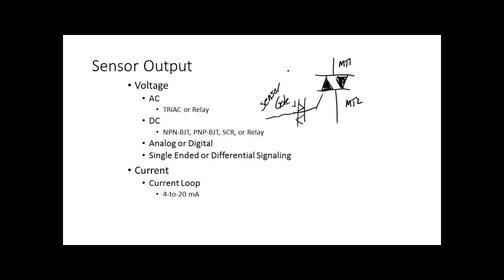So that means as far as how fast we can switch, solid state devices are far faster than relays. Now, as far as turning lights on and off, we have no problem. But some of the things that we run into in controls, we cannot do with a PLC that's got relay outputs. Call it a pulse train output, PTO outputs. These generate a high frequency digital pulse output. Pulse width modulation, these guys usually run about 15, 16 kilohertz. You cannot do pulse width modulation with a PLC that's got a relay output. So these guys are going to have what? They're going to have solid state outputs.